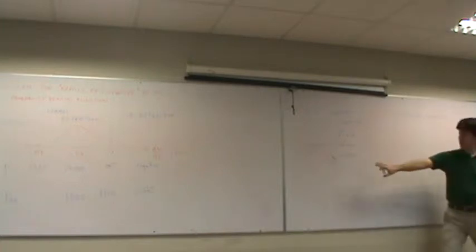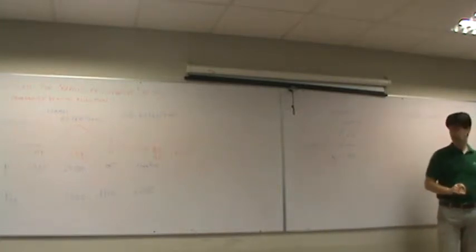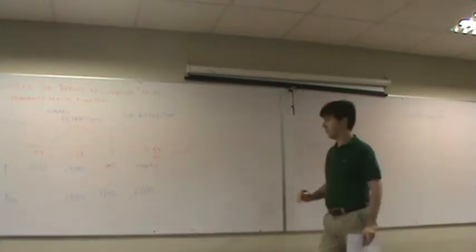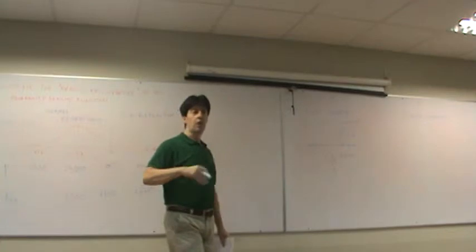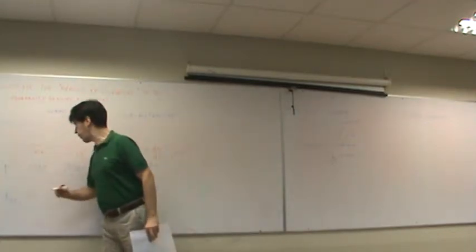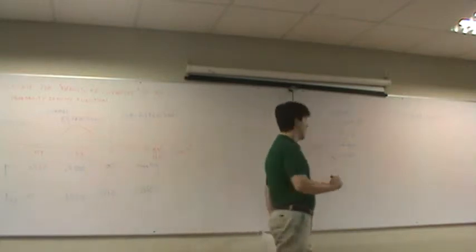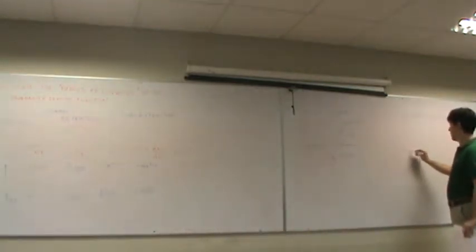So what will be the distorted geometry for this situation? What will be the equivalent Earth radius? You do the calculation, you find the equivalent Earth radius is infinite. That is, the distorted geometry is a flat planet.